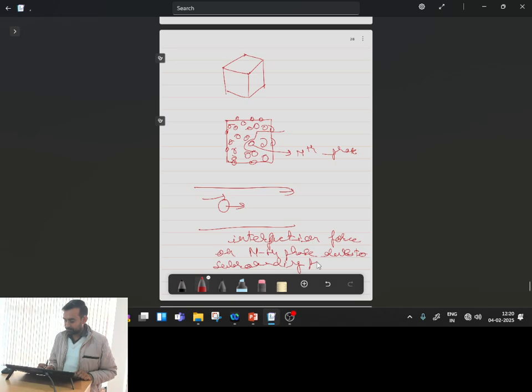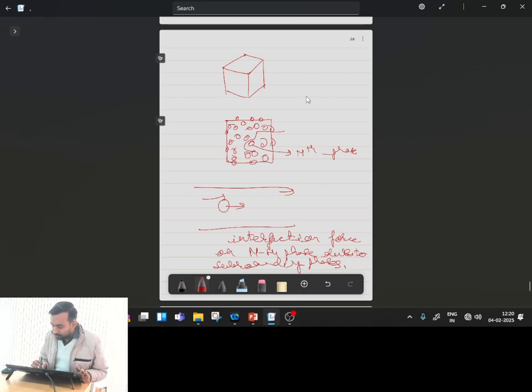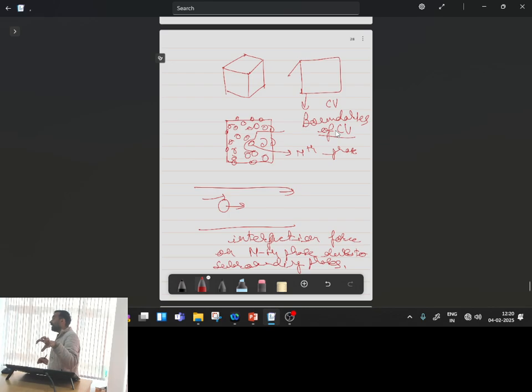Is this point clear? So in a single phase situation, only two types of surface forces were coming into the picture, which were the pressure force and the viscous force. And for a single phase flow, because the entire control volume is filled with the same type of fluid, these viscous stresses and pressure forces were only acting at the boundaries of the control volume, because within it the shear stress and pressure were balanced.